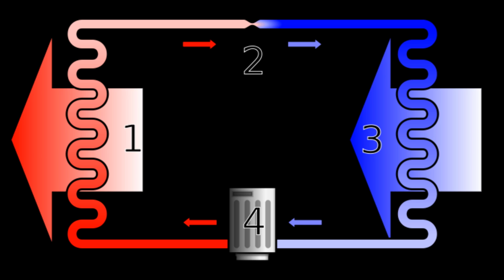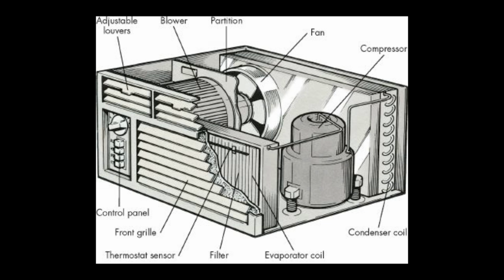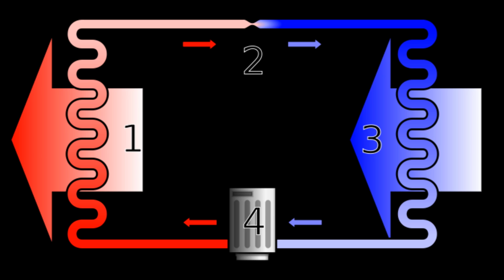The actual cooling liquid stays the same. It's never exchanged. It just circulates and turns into a gas and back into a liquid. But it is cooled down and heated up without actually adding or taking out heat. And then once it is hot or cold, heat is actually added or taken out in addition, thus keeping the whole cycle an overall temperature change of 0, but you can take in heat as it is cold and give off heat as it is hot, and thus you can pump heat through an additional thermal gradient and pump heat from a cold place to a hot place.